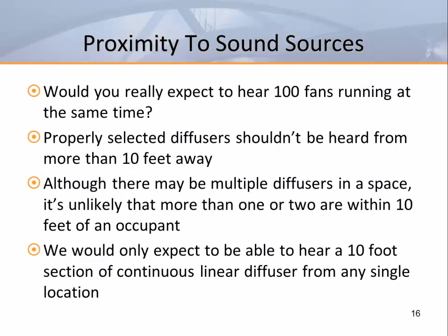Would you really expect to hear 100 fans running at the same time? They would need to be extremely small fans in order to be heard from a single listening point. There's a rule of thumb that says properly selected diffusers should not be heard when they're more than 10 feet away from the listener. So if we have two NC20 diffusers that are more than 10 feet apart, it's unlikely that we'll hear both from any single location.